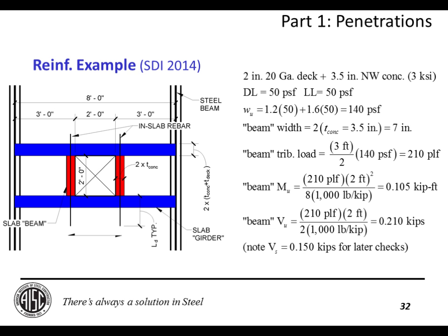And again, SDI to the rescue here with their floor design manual. They provide sort of an analytical construct in order for you to take a look at whether your deck needs to be reinforced or not. And what they recommend is essentially just an in-slab fake beam and girder system.